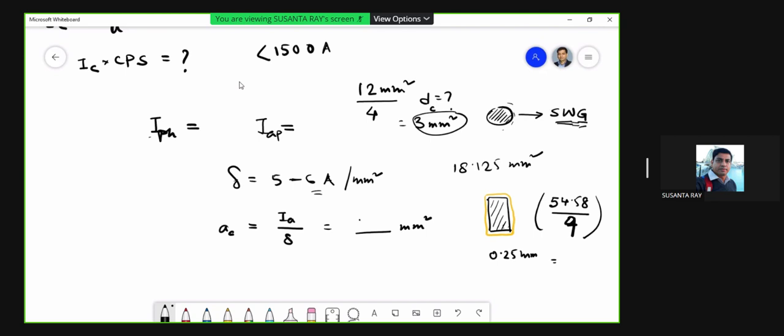Lead acid battery has a voltage of only 2 volt per cell. If you take only one cell, you can get 2 volt. The quite common one is 6 cells in series, so generally we get the 12 volt battery. 12 volt batteries are quite common for cars, four wheelers, and other things.